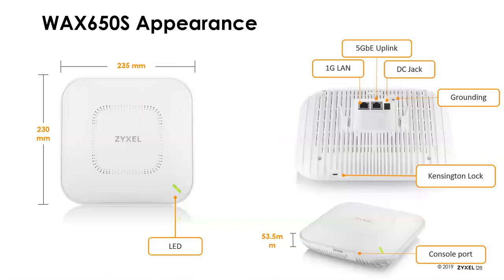So it should be noted here that this guy, if you're powering it with PoE, it requires 60 watt 802.3 BT PoE power. It does not work on the 802.3 AF or 802.3 AT PoE power standard. So you do need to be sure you're buying an injector or switch that supports 60 watts of power, or alternately, we do sell an AC adapter. Although generally there's not AC outlets up in the ceiling, but if you need to, we have the ability to power this via AC.